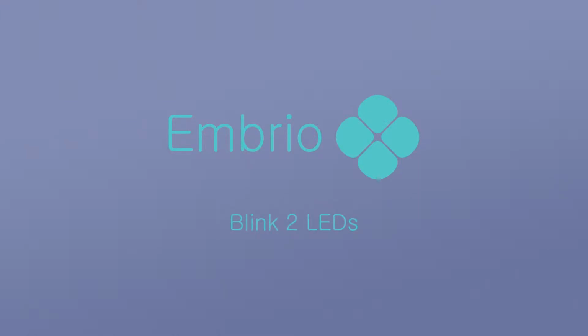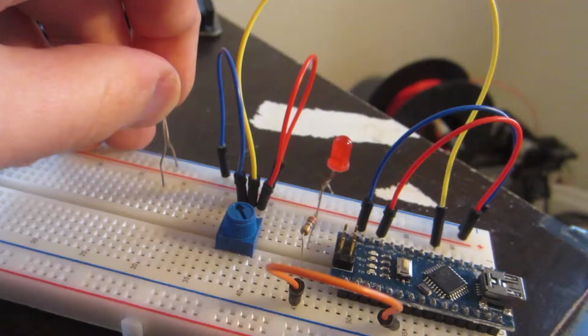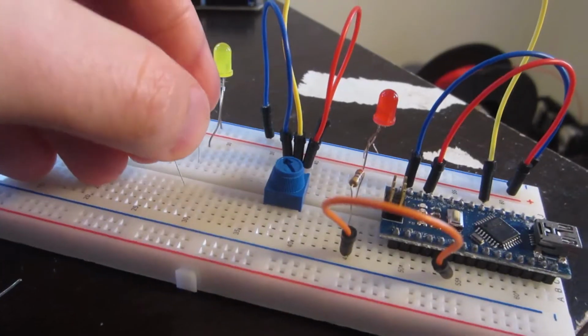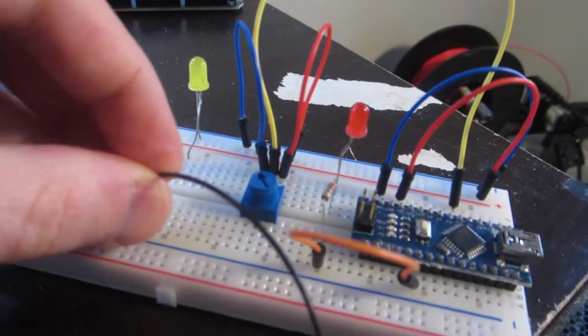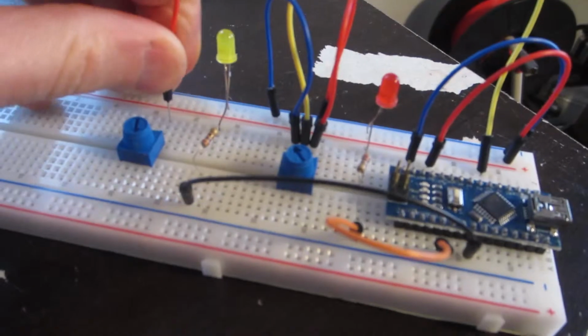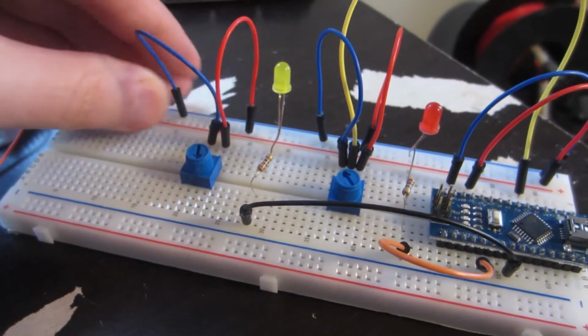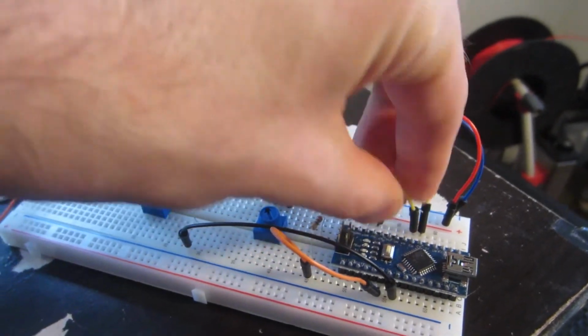In this project, I'll blink 2 LEDs. In Embrio, this is almost as easy as blinking 1 LED. I'll start with the results of the last tutorial where I controlled 1 LED with a potentiometer, and just add another LED and potentiometer the same way. I plug this new LED into digital pin 5, and the new potentiometer into pin A3.